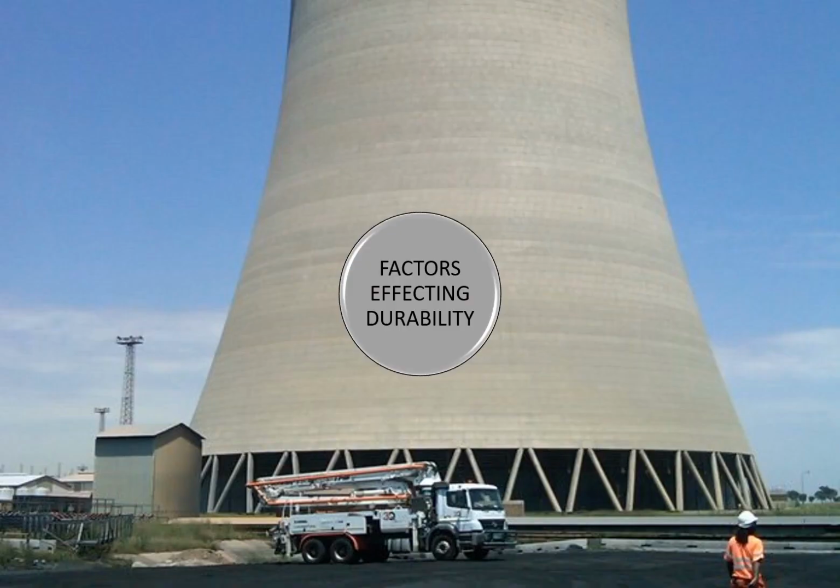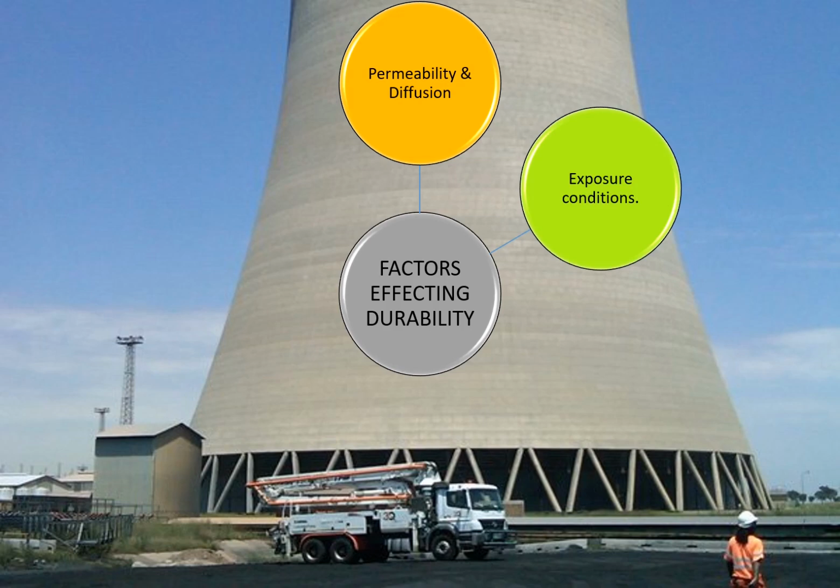Now, the factors affecting the durability are, first, permeability and diffusion properties. Second is the exposure conditions, like normal exposure, moderate exposure, severe exposure, and very severe exposure. Depending upon the environmental conditions, the exposure conditions are defined in the codal provisions. IS 456 also gives a clear indication of the different types of exposure conditions, and based on them, the minimum cement content and the maximum water cement ratio are established in the standards.